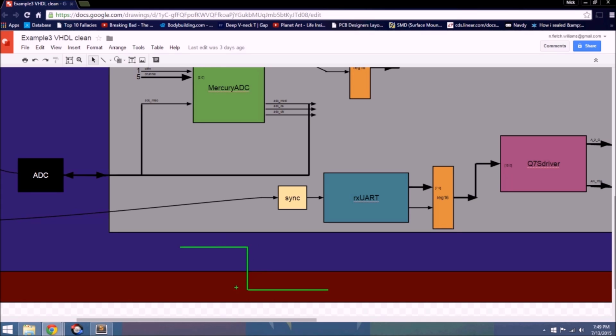So it kind of looks like this, and we'll say the clock cycles of the clock that runs this hardware occur here. Now since the falling edge here occurs at different times than the rising clock edge, that means it's asynchronous. This sync hardware simply buffers the signal and forces this edge to one of the clock signals, making an asynchronous signal into a synchronous one. The sync hardware adds a 2 clock cycle delay to the signal, so the output will become something like this. So here you can see it takes 2 additional rising edges of the clock until this falling edge is propagated.